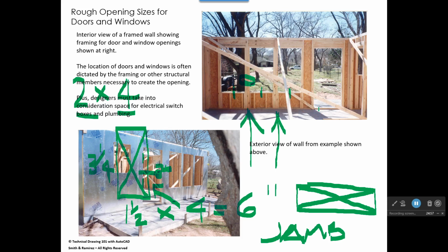So if we look at it from the inside of the house, the door swings in this direction right here. That means our light switches go right there. Okay. Now, probably the first switch as soon as you walk in there is going to be the porch light. And then next to that, there's going to be another switch that may be an overhead light in this living room. There may even be a third switch in there that turns on a ceiling fan. So the electrician comes in, and the electrician has to mount an electrical box for each one of those switches.